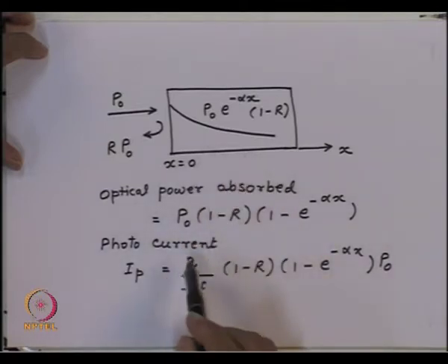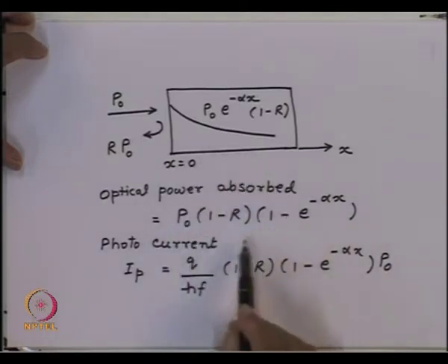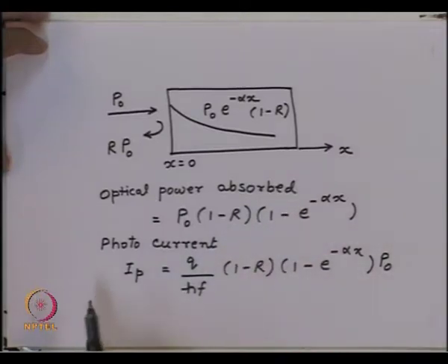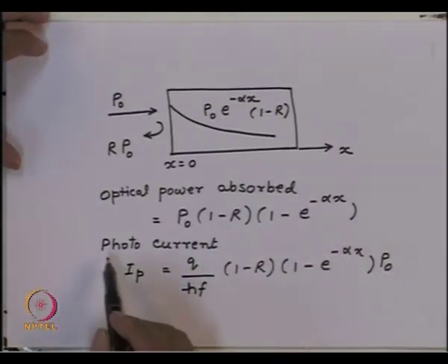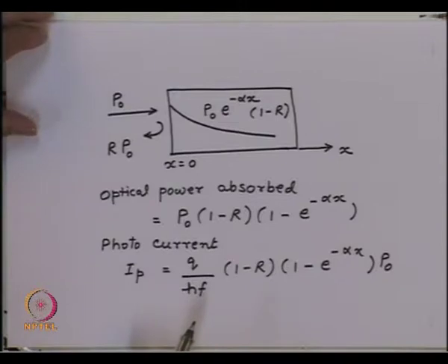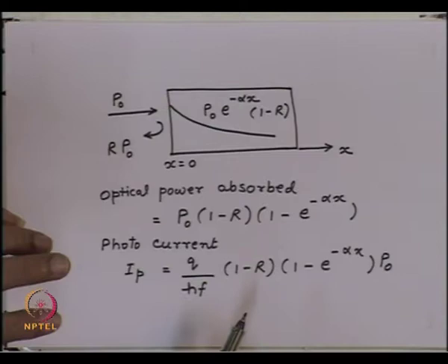And if you could collect the carriers generated by this photo absorption, then we get what is called a photocurrent. Here we are saying that when a photon is absorbed inside a material, a carrier, an electron hole pair, is generated, and if you create a mechanism by which this electron hole pair can be collected, a current will flow in the external circuitry, which we call the photocurrent.